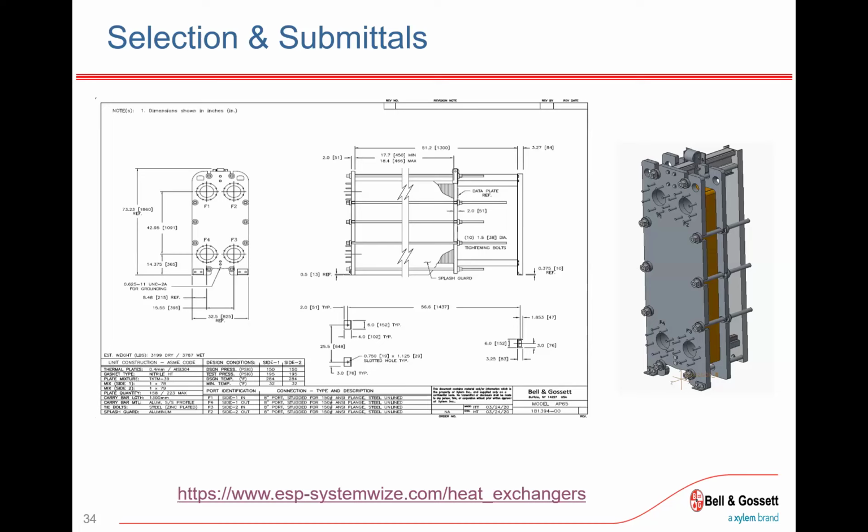So for instance, if I were to go 500 gallons a minute, 60 feet of head, and let's say an e1510X, you have your conditions, you have any motor details. The default is non-overloading, but if you wanted to change it for duty point, you have some constraints maybe on your motor horsepower. You want to match the existing horsepower, but at the same time maybe stretch the conditions. You can adjust any of those in there. I just put the conditions in, selected the e1510X. That's the end suction base mounted unit with the onboard drive.